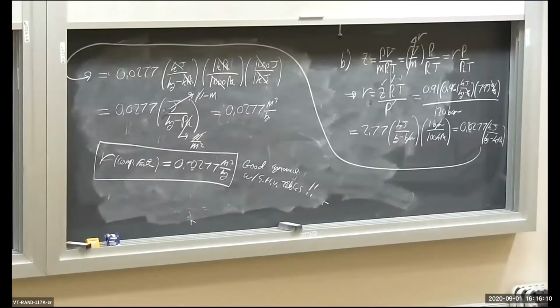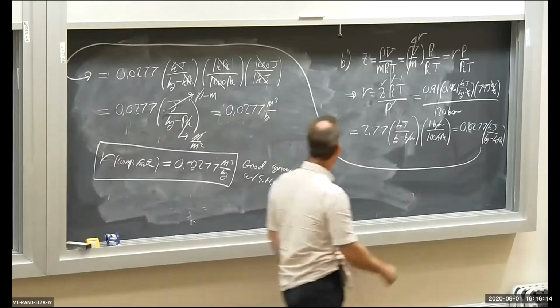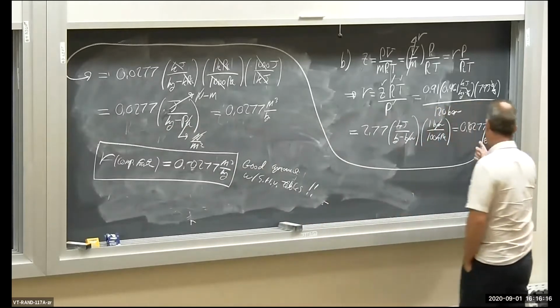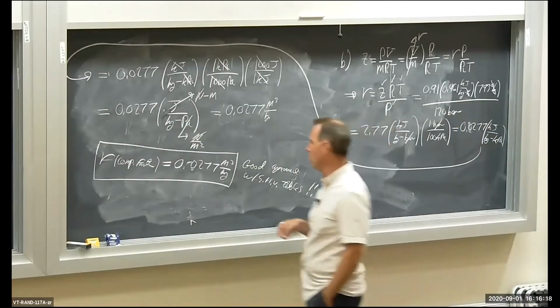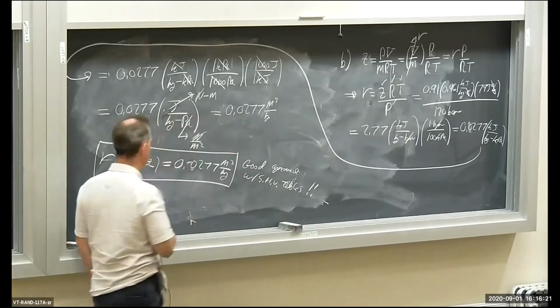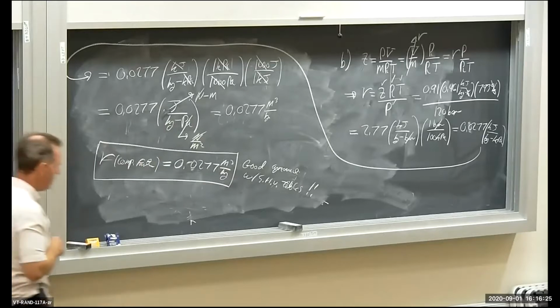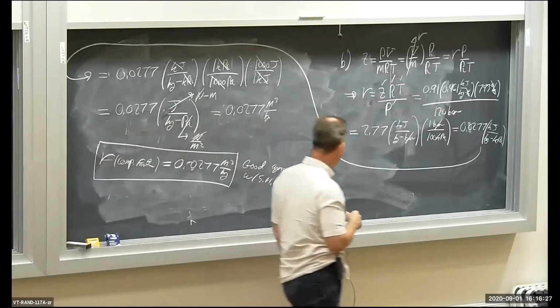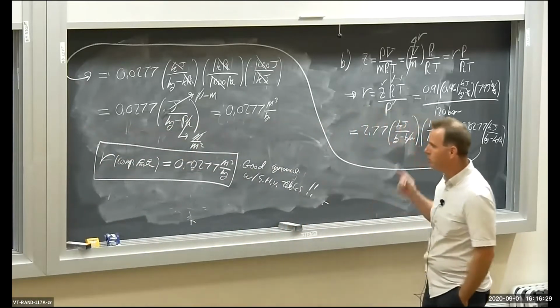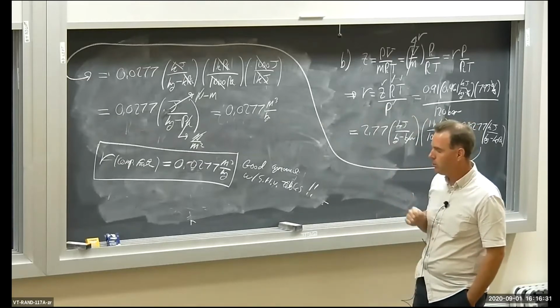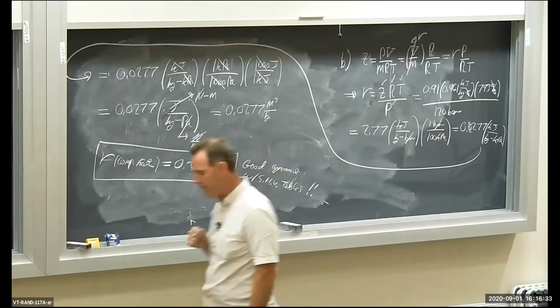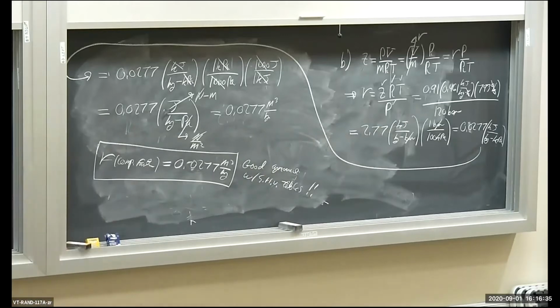We use the compressibility factor found, Z of approximately 0.91, and we calculated a specific volume of 0.027 cubic meters per kilogram. Very close to the value out of the steam table or the superheated vapor tables. Very good agreement between use of the compressibility factor Z to calculate specific volume and the actual value from the superheated vapor tables.